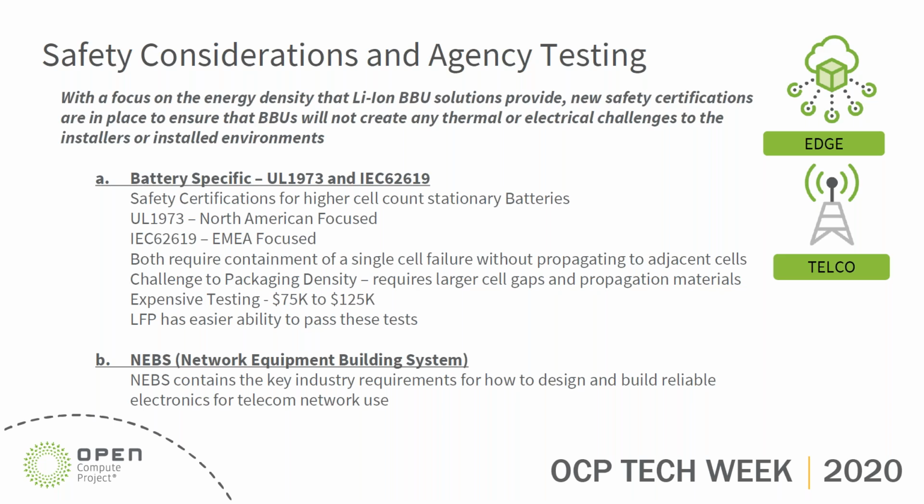And the reason I bring this up with certifications and the cost is that every time you do a different configuration, so you might have a box that, let's say, is 2 kilowatts. If you have one that's 12 volt and one that's 48 volt, well, those are two different systems. Each one's going to require that certification. If you have one that's 1 kilowatt and one that's 2 kilowatt for the same 48 volts, depending on how you design it, you may be able to only have to pass that test once and have that test be relative to both power levels. So these are things that we have to have figured out on the front end.